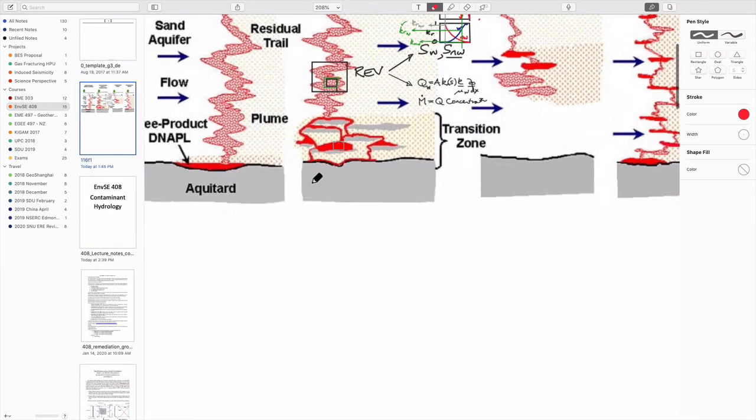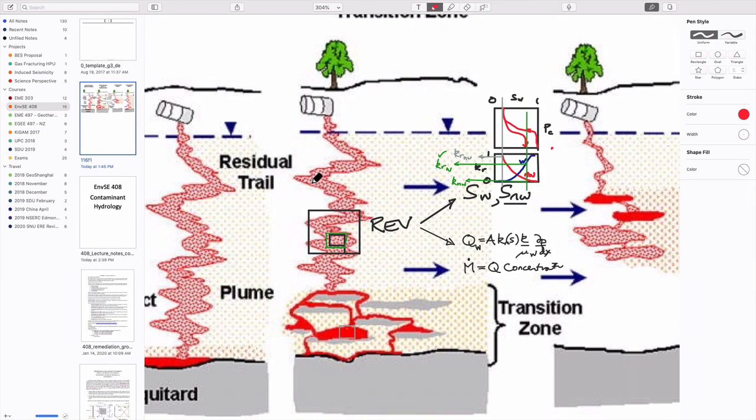And so we've made the point that if we're in a portion of this aquifer, which is partially saturated with NAPL, we know a portion, this is fully saturated now, and so if a portion of it is saturated with the NAPL that fills up the pore space, then we have some way from these capillary pressure versus saturation curves, and capillary pressure versus relative permeability curves, to be able to define this volumetric flow rate, because we have this for a given saturation.